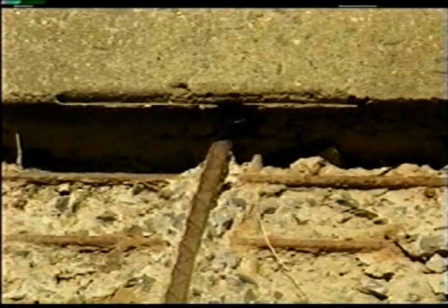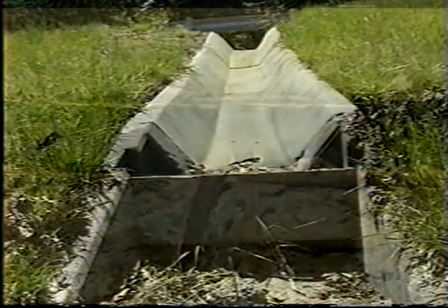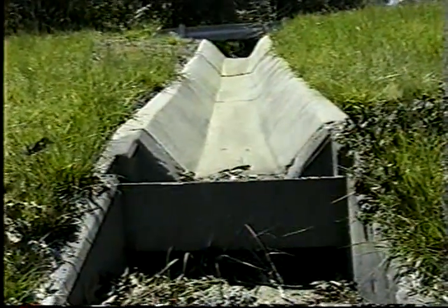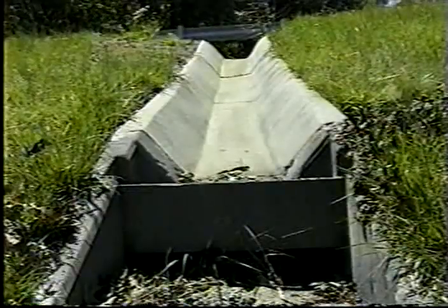High velocity flows containing large quantities of stone and rock scour the culvert bottom. Scour may be reduced by securing steel plates longitudinally along the bottom. To prevent erosion, energy dissipators are sometimes placed at outlets of culverts and sewers. It is important that these be inspected periodically, particularly after major